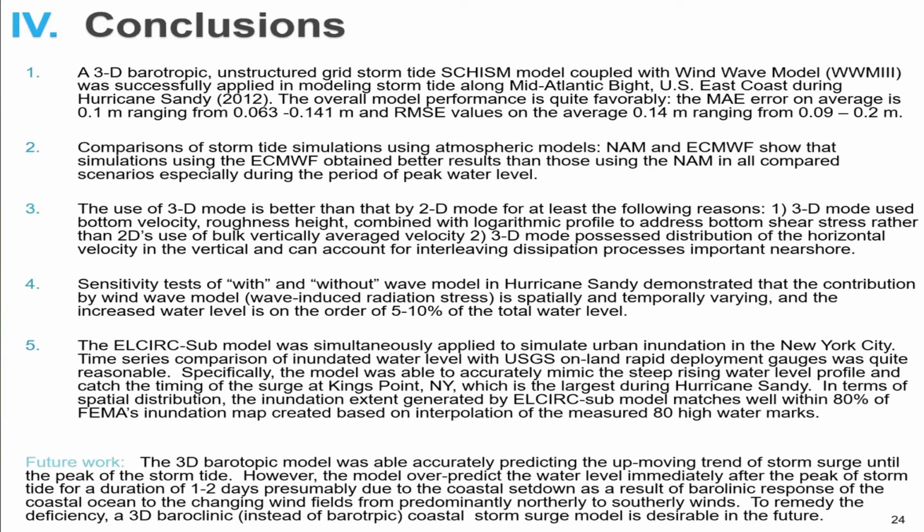And number four is a sensitivity test with and without waves. The waves do contribute to the total water level, spatially and temporally varying, and increase water level on the order of about 5 to 10% of the total water level. Lastly, the LSEG subgrid model was applied to simulate inundation in New York City.